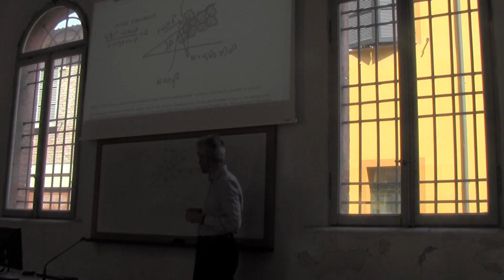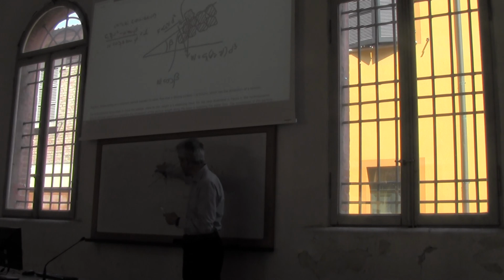But what triggers this displacement of the boulder is the wave running up. It's not the boulder by itself that is unstable. The boulder without the wave is stable. Then stability is undermined by the action of the wave, and the way it's undermined is that the boulder is removed by a force that is pushing it up. Of course, it doesn't stop at the top of the groin. Once it's removed, it's taken by water into the sea.